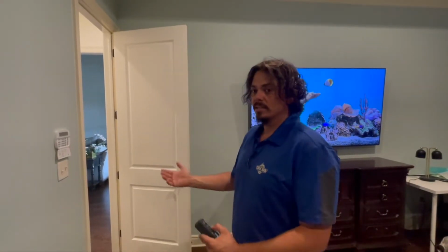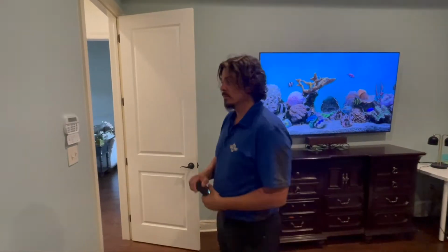Now, we're going to leave all these doors open. There's another reason why, whenever you're walking through the house: one, you get a glimpse of what's happening, so that once we get into the attic, we can navigate and know where we're at and what problems we should be looking for. But also, I get to leave all the doors open, so that throughout my test, I'm not allowing the house to create any pressure differential issues because of open or closed doors.